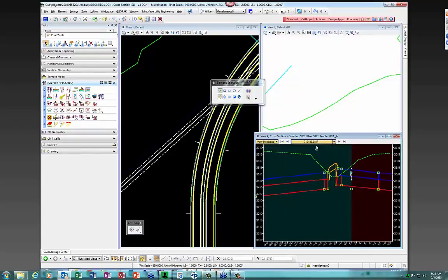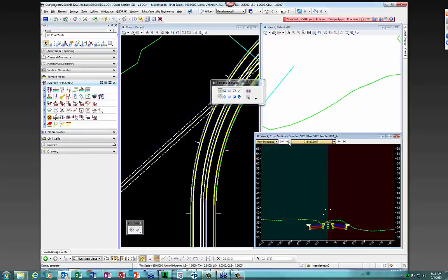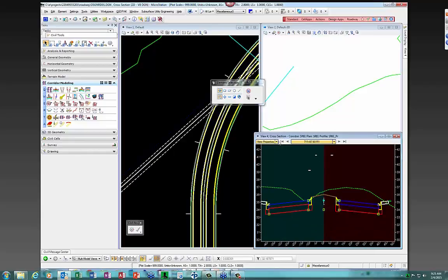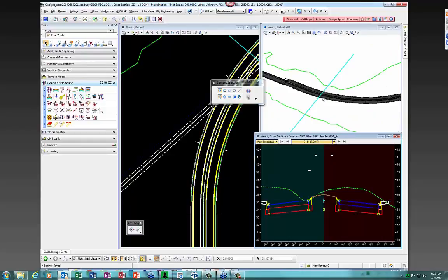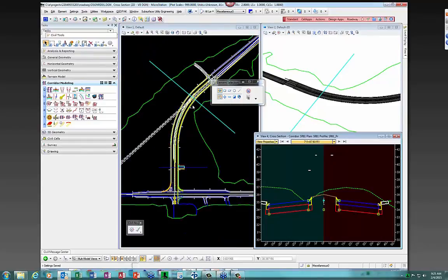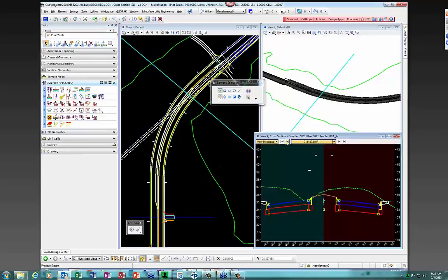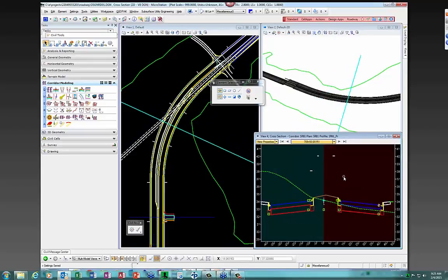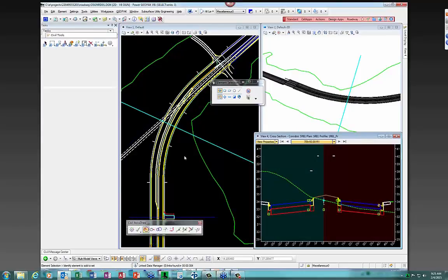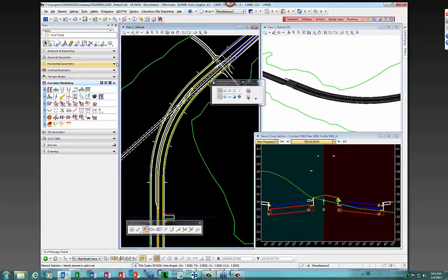as you go through that. It looked like it was in the middle of the turn lane at 712. I'm going to set this to center on my current offsets. I'm going to press Control F to file save settings so that this is always saved this way. Then you can also see that I'm in this corridor right here on the curve. I'm also in the corridor here on the curve, and if I move back and forth, it's just a normal unsuperelevated roadway.